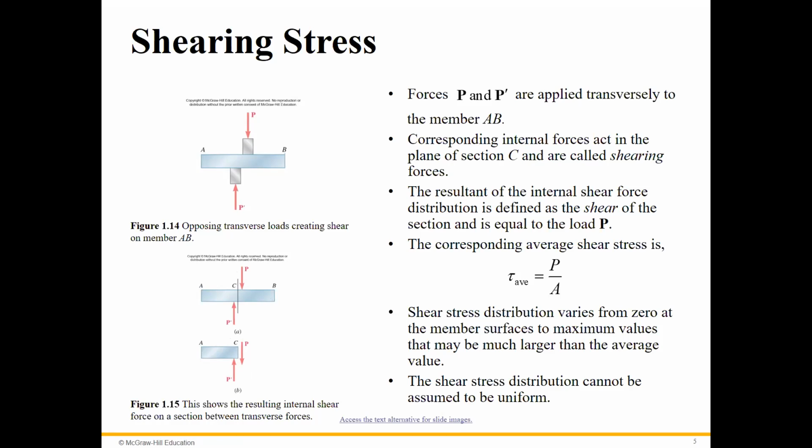So it just picked some easy problems and said, okay, we have these 2 forces in opposite directions, so we have this shear force and put it here, right? Because now we're just focusing on this formula. But your question is a good question. It's focusing on the statics. If we have any other problems, not necessarily like this, maybe a bunch of forces, first of all, we should find the shear force at individual sections and then use that force to